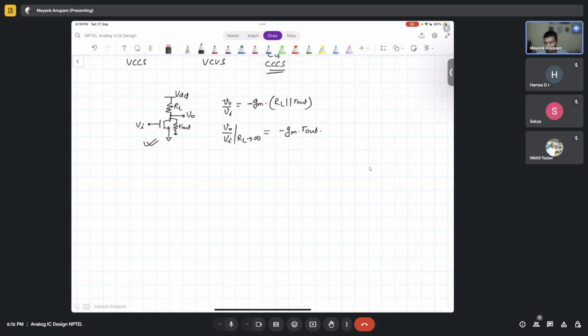It's basically the gain of the MOSFET, assuming that the output load is infinite. That is what it is. Got it? So basically, intrinsic means we need to make the load equal to infinite. Intrinsic, as the name implies, means whatever is only because of the device itself. There is nothing else present. Whatever is because of the device only is called intrinsic. The meaning should be very evident from the name itself.